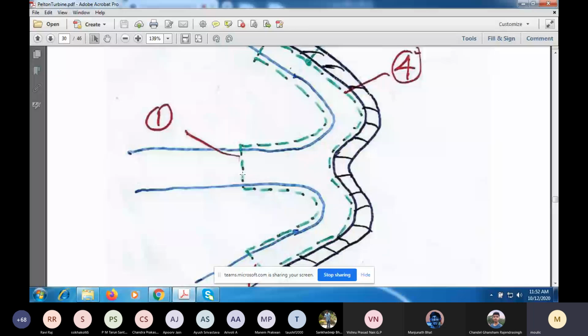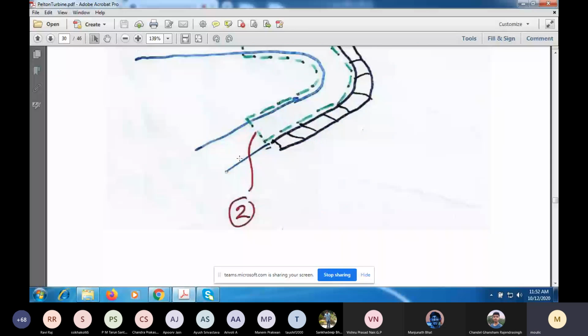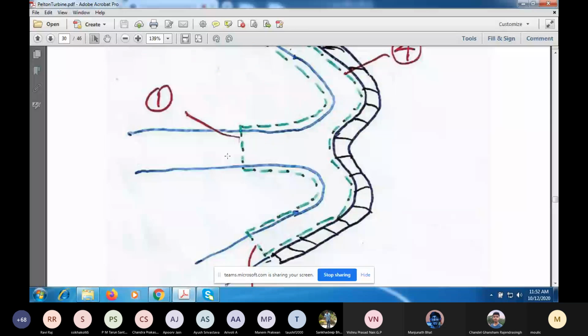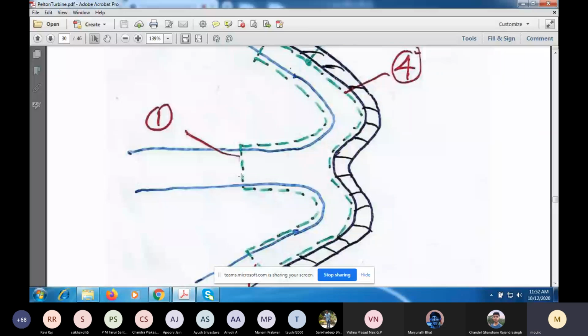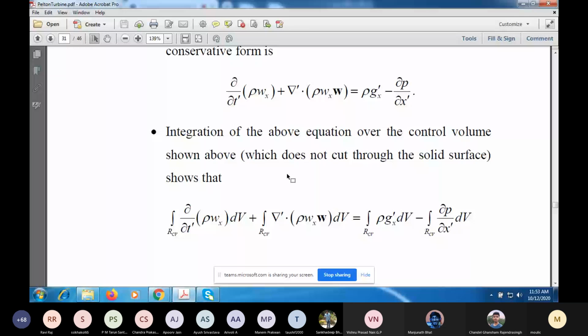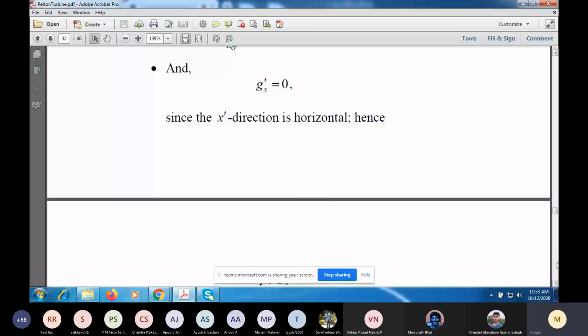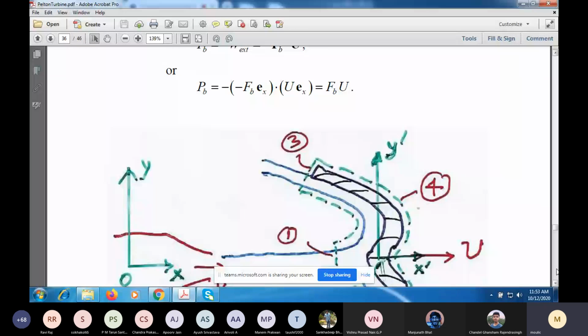And there is work done if fluid is displaced. Now this green boundary is translating to the right, and the fluid is also moving. So the rate at which the fluid is displaced is determined by the velocity relative to this surface, which we are calling W. So the work done at that interface, the surface of the control volume, will be P1 A1 times W1, the rate of work done.